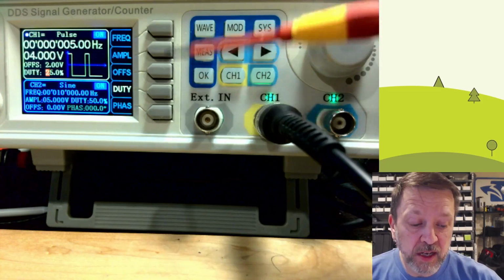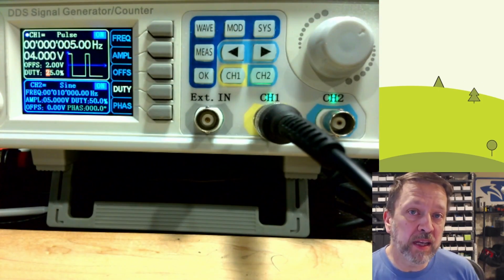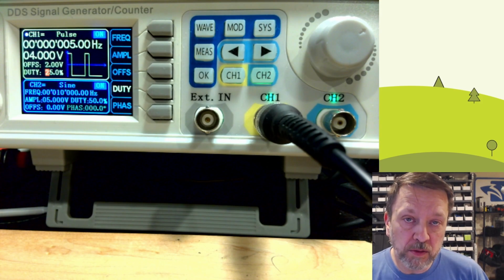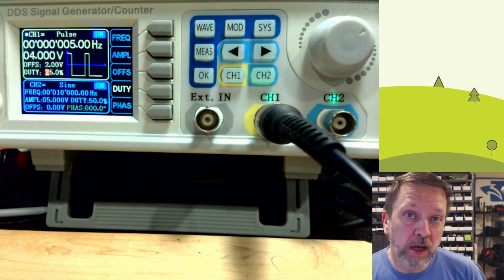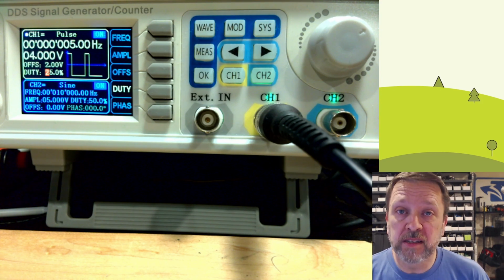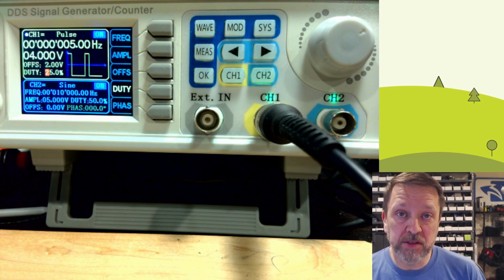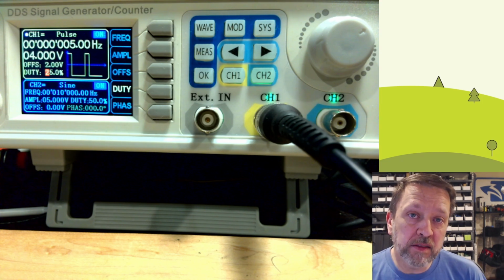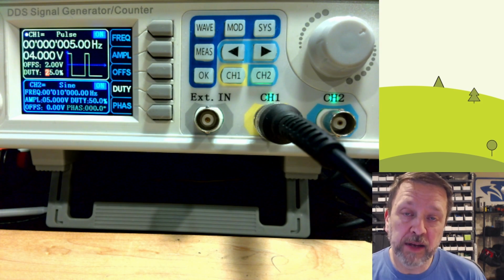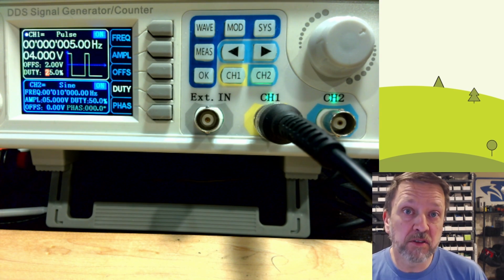Now that we understand how we use the signal generator and adjust the parameters here and what the outputs look like, let's talk about what we would use this for. Broadly speaking, I use this for generating interrupts for testing. A good example would be doing long-term sleep-wake testing, something where I'm looking at the interrupt to wake up and then go back to sleep, and I want to run it all night. I don't want to sit here and push a button. Pushing a button is another classic example.